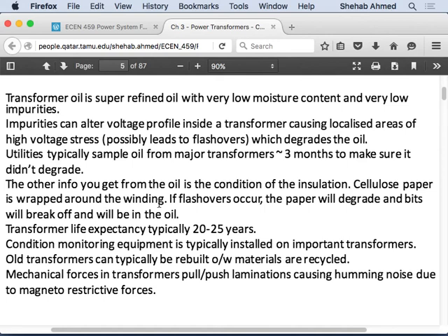If you have windings, for example, that are wrapped in polyimide, polyimide is a very good insulator. It's excellent, or Kapton. Kapton or polyimide is a very good insulator. But you bring water to it, it ruins it, right? So electrically it's great, but you cannot bring water. If it touches water, it will ruin it completely. So we put this.